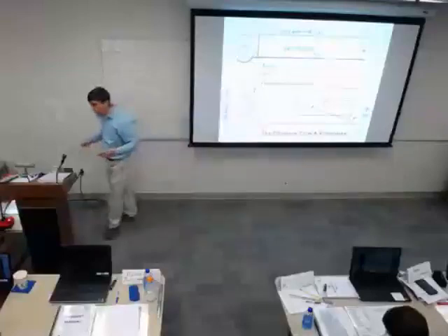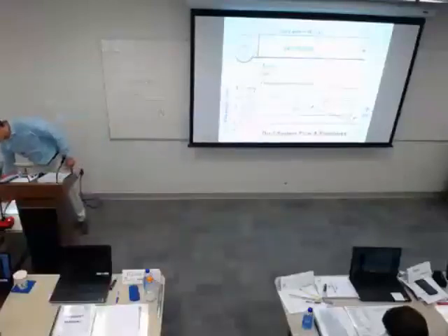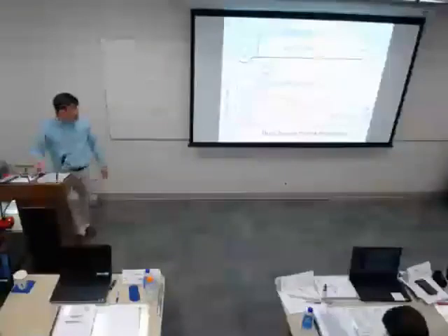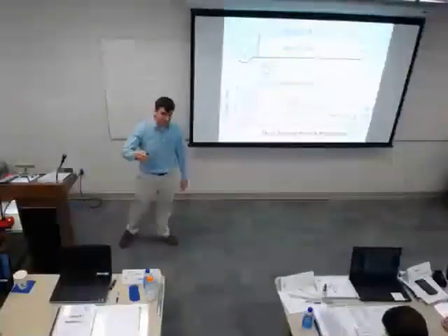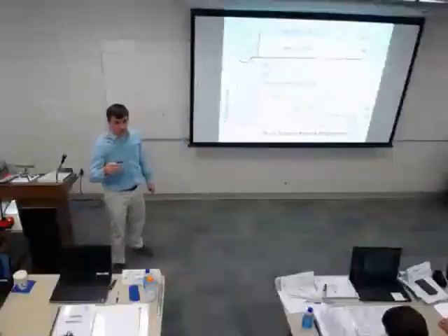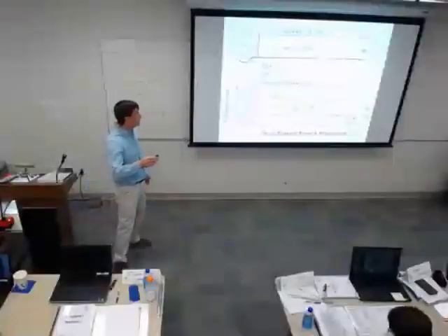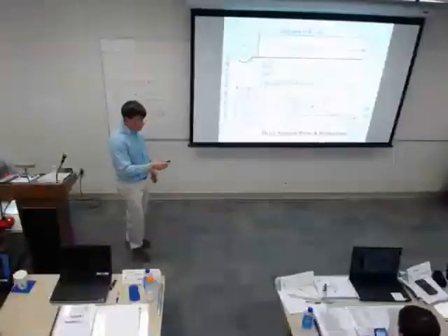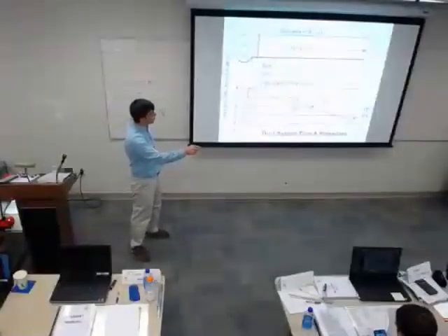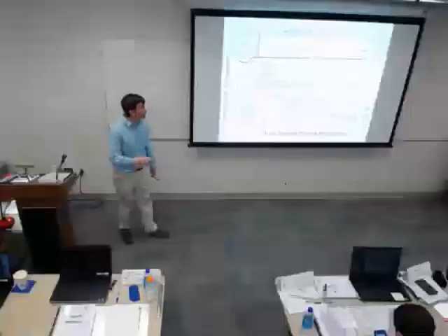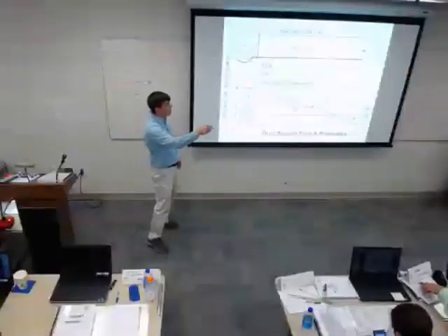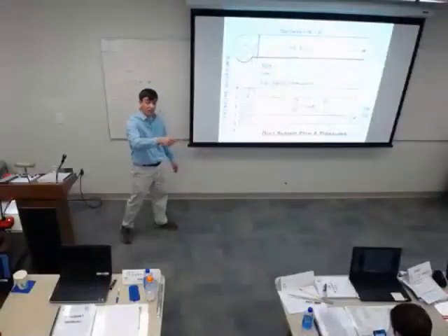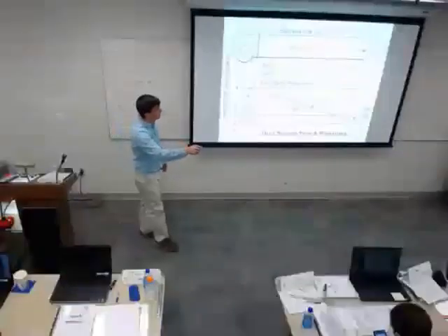With 2 inches of water column as my velocity pressure, I can figure out what my velocity is from that. Anybody remember? Learned that equation this morning? That's going to give me my flow rate. It was this funny one, 4,005 times the square root of the velocity pressure. Okay, so I plug in this 0.2, take the square root, and remember this was at standard conditions. This 4,005, we had to make a correction for density if we're outside of standard conditions.